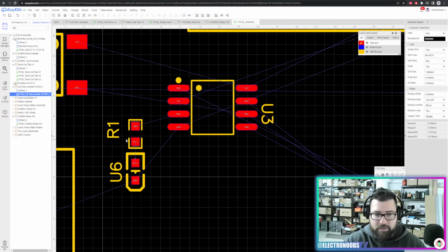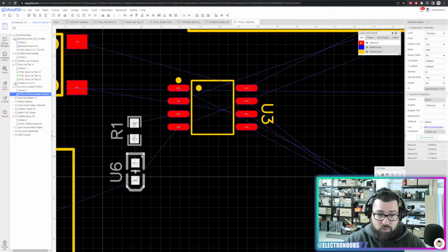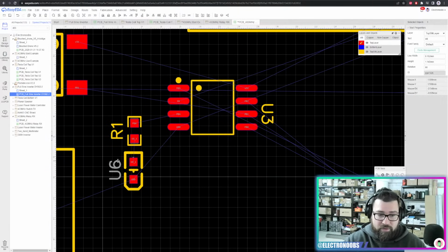Make sure that you place the name of the resistor so you can see it, because if you place it like this, when you solder the component, you won't see it. And this is very important because when you solder the components, you will see the schematic and then your PCB, and you want to see the silkscreen clearly to know which resistor is which. So make sure that it is very visible.